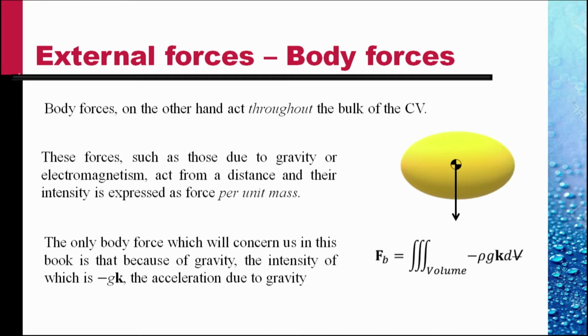So, the total body force is obtained by integrating over the volume the mass of the body, rho times dv, times the acceleration due to gravity, which is minus gk. So, this expression gives you the total body force.